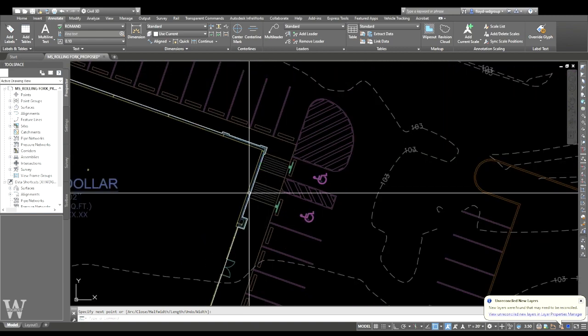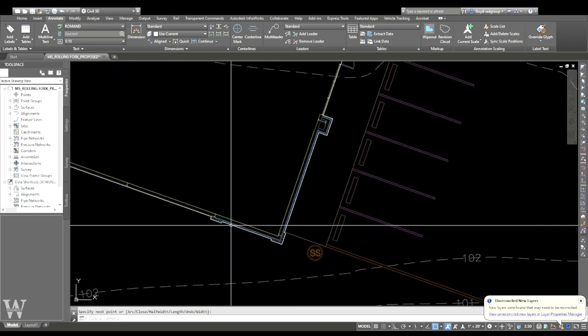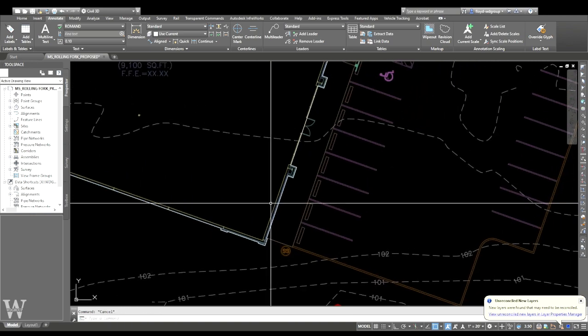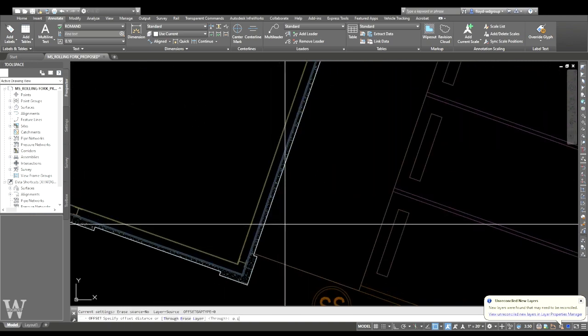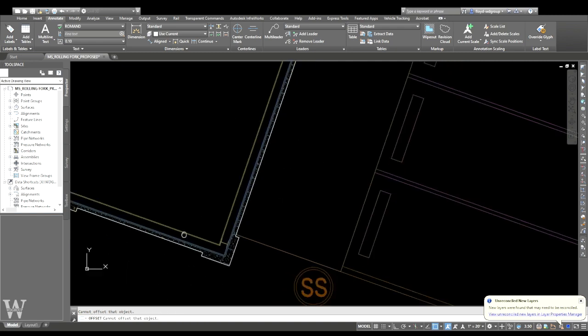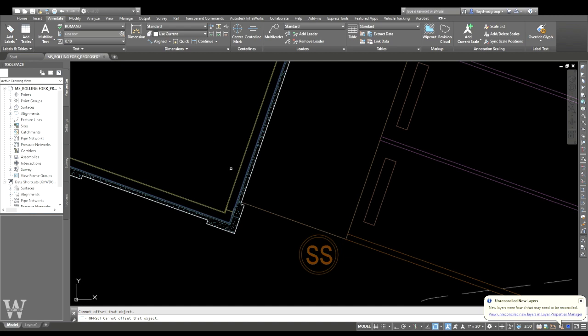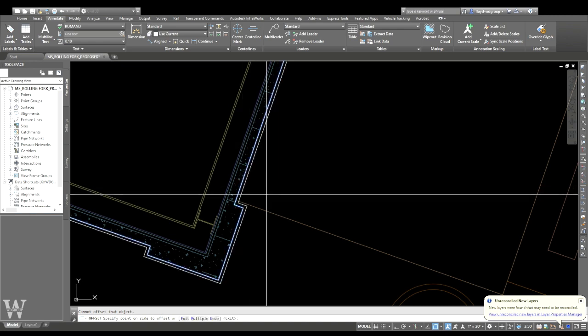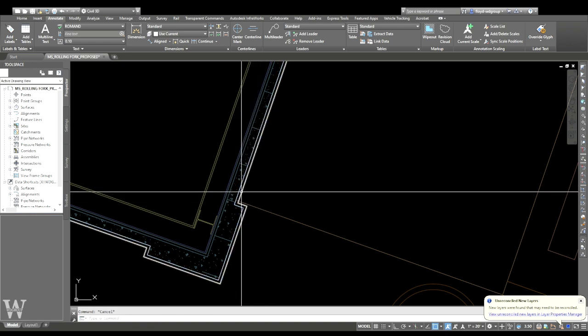And so I hit every place right there. I hit a point where I want an elevation change. Now I'm going to just hit J for join and join that polyline and make it one. All right, now we talked about being offset. That's the finished floor. The sidewalk, the grass outside, the HVAC pad, everything's going to be at a different elevation than the building. So, but I can't do a vertical plane, so I'm going to offset it a 1/10, okay?